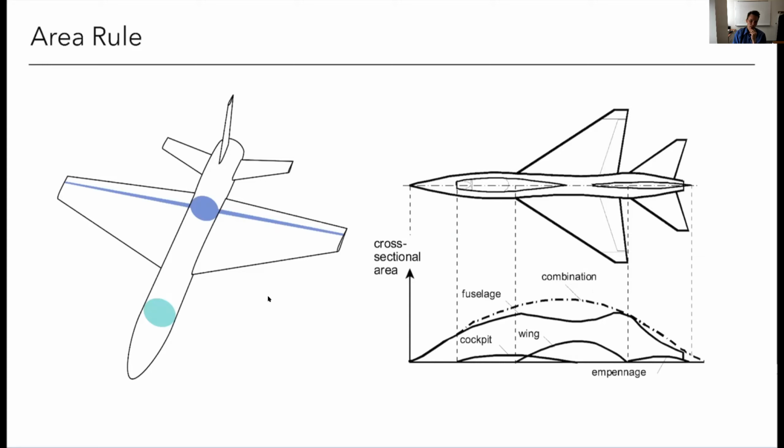It's actually more complicated than that. We need to take cuts not just in this normal direction, but along, let's say, these Mach contours, the Mach lines, or the Mach angles rather, of all the various Mach numbers that we're going to fly at. If we may fly across a range of Mach numbers, we've got to make sure the area distribution is smooth across many different ways to cut up this aircraft. So that can be a complex procedure.